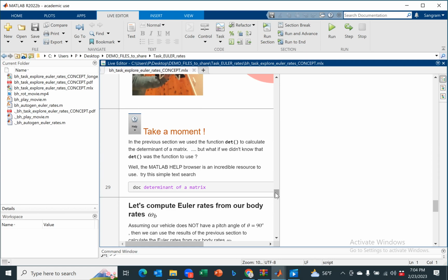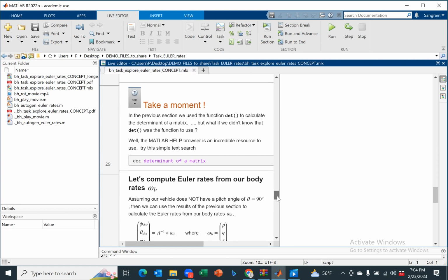You add that Simulink block to your actual code, and then use MATLAB Coder to create the C file, and then you can burn it on a flight platform. You can do the exact same thing with Pixhawk. MATLAB has a direct pipeline to the Pixhawk. You can connect Pixhawk to MATLAB and implement the model.